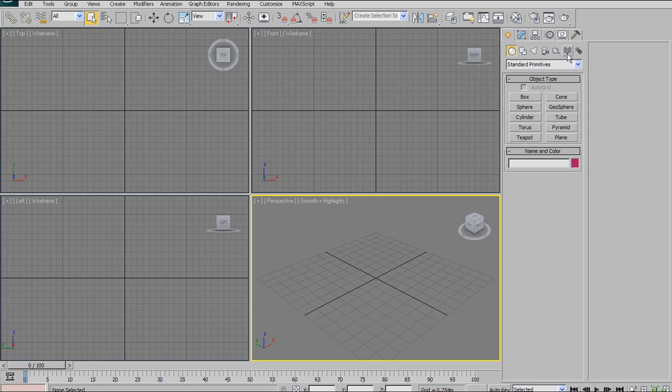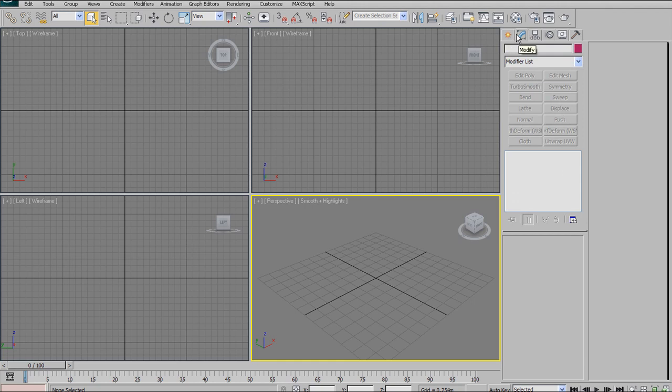We're also going to be looking over here to the right. You see this little box of tabs up here. This is known as the command panel. We're primarily going to be looking at two buttons of this command panel. The one that shows this little spark here, which is your creation tab. This is what you would use to create anything new in your scene. So geometry, lights, cameras, any types of particles, or even setting up rigs and things you would do from your creation tab. But we're going to be focusing primarily on creating geometry in the form of standard primitives, and well, basically that's it.